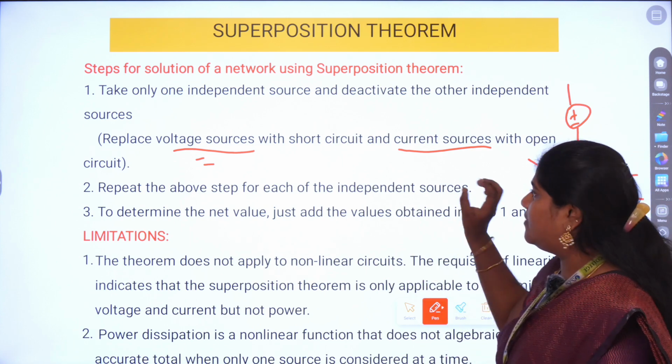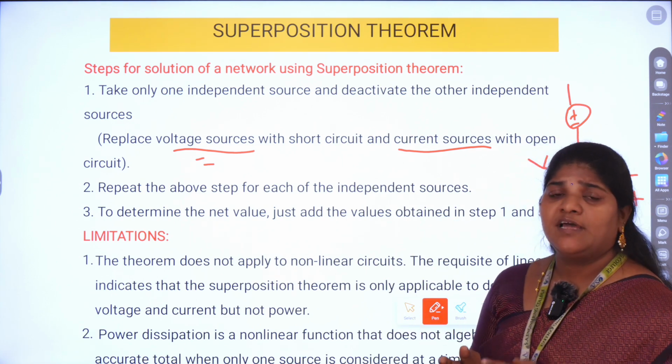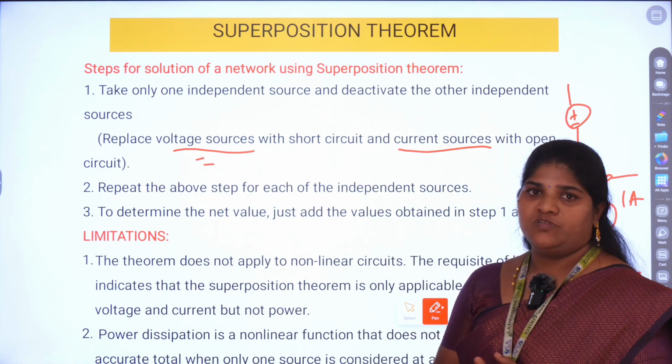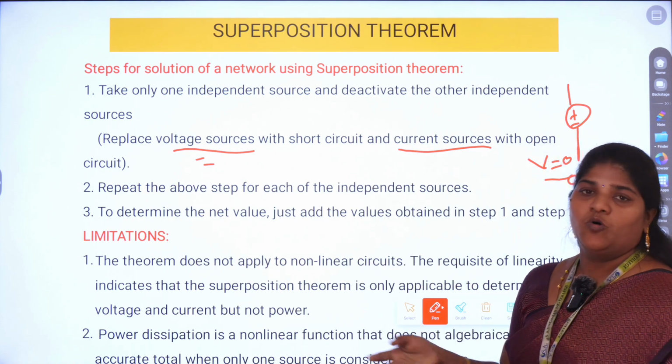These two things are very, very important because we will be playing the game with only two sources, either a voltage source or a current source. If it is a voltage source, make it short circuit. If it is a current source, make it open circuit.